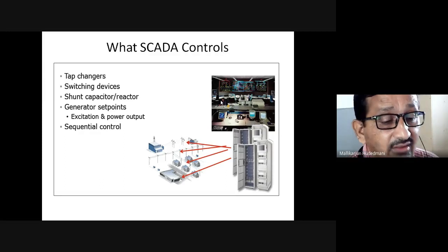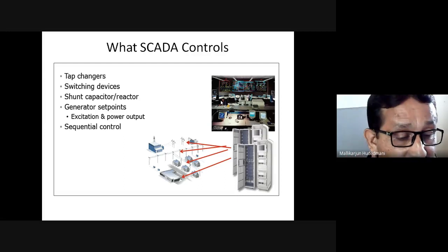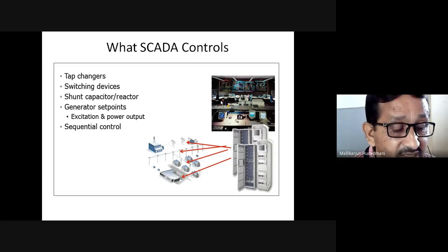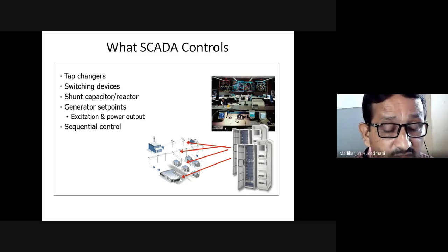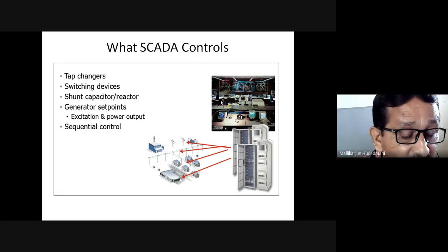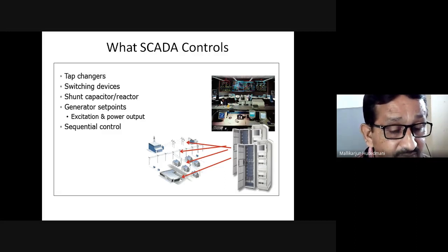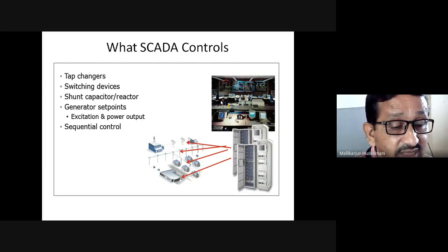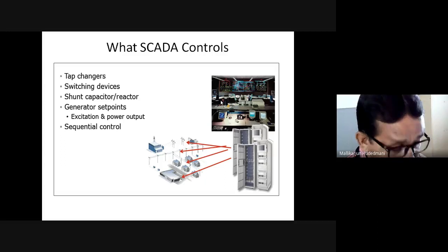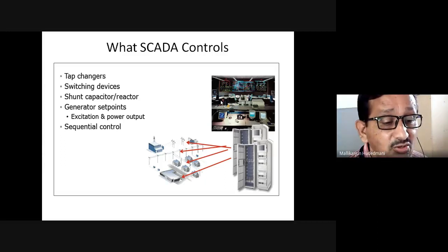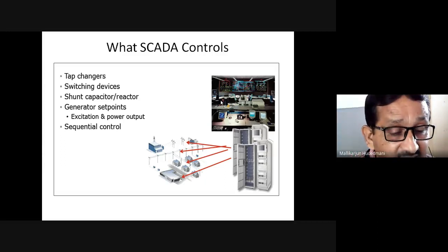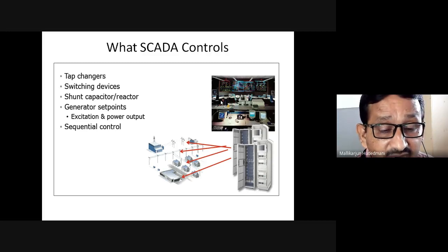It definitely triggers a tap changer, changing the tap, decreasing or increasing as per the requirement. Switching devices, isolation or any line coupling or circuit breaker operation, closing, opening, putting in service, removing from service. Switching devices like a shunt capacitor and reactor can be controlled from this. If any power factor control or reactive power balance is there in the system, it can be configured such